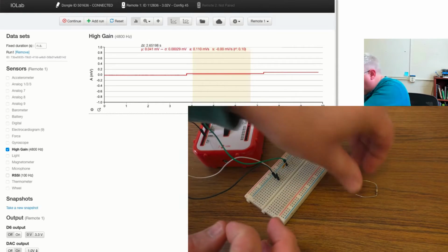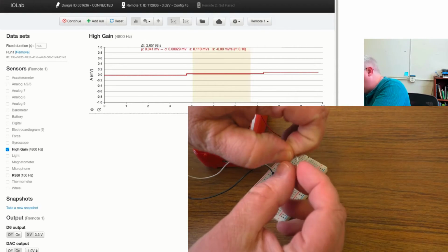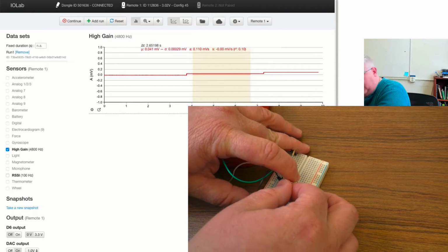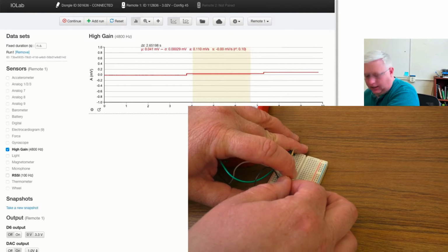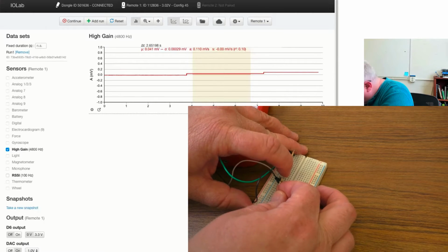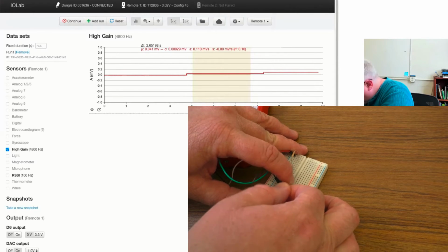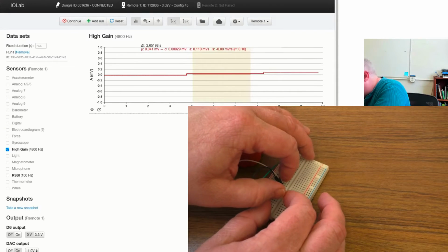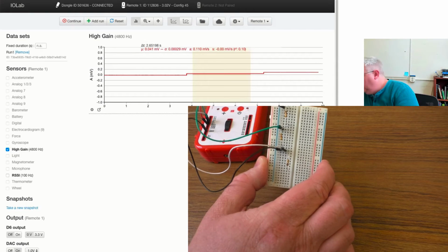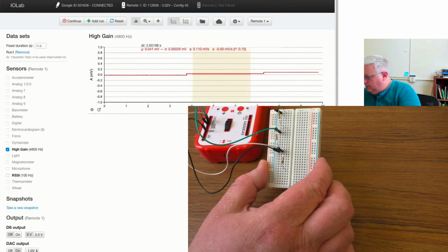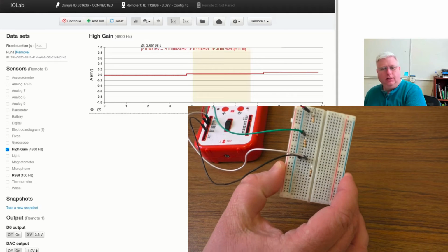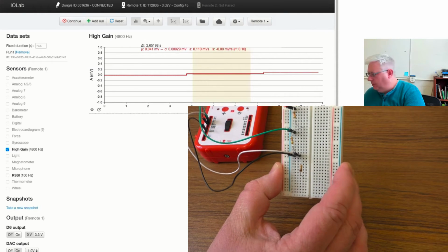And then the 1 ohm resistor, which acts as our ammeter to measure current, I'll put that between 17 and looks like 25 in the picture. And so there's nothing special about these holes. You could put them in whatever holes you want, as long as you do it the way the breadboard works. I'm just trying to keep it consistent with the lab manual in case you're wanting to follow along with that.